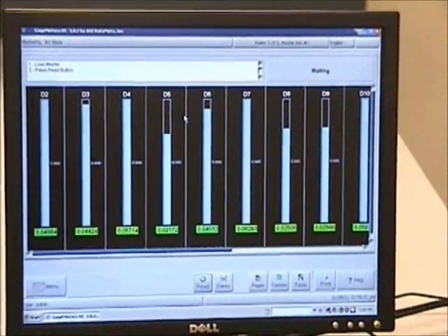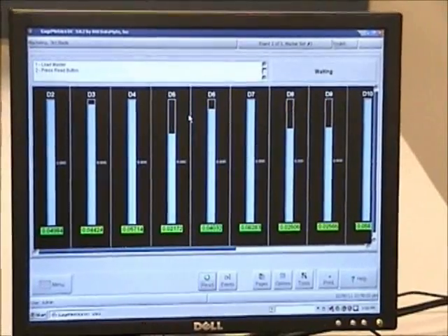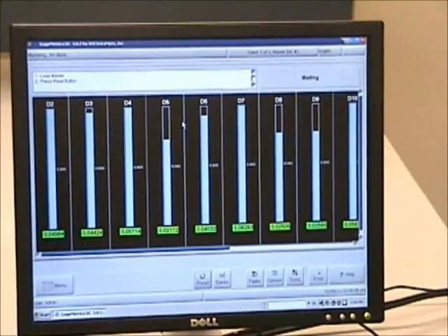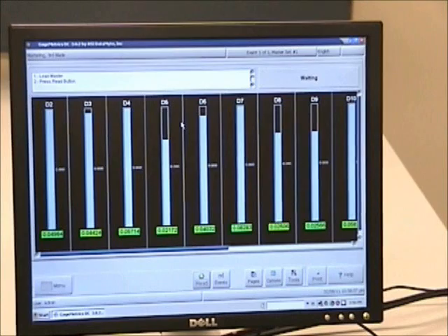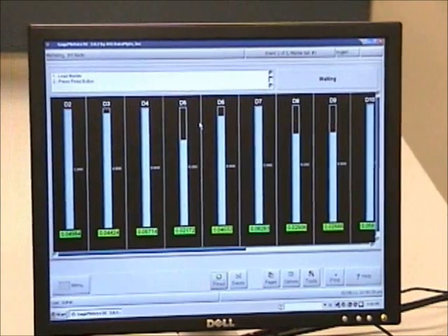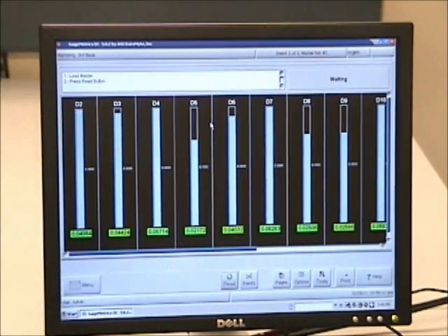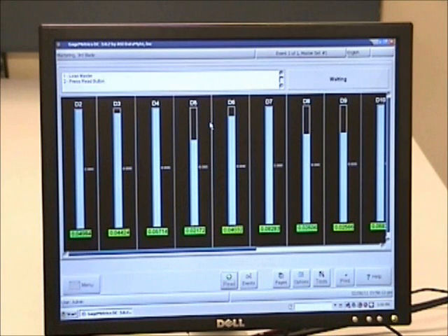This ensures that if you ever have a probe that is loose in the gauge or damaged, it should show up in a mastering fault, because your mastering should be very, very accurate compared to yesterday's mastering or next week's mastering. Nothing should vary a large degree unless something mechanically is moved. That's what this is for.